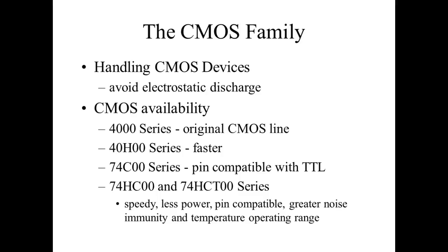So in the old days, 4000 series was CMOS, 7400 series was TTL, and they were not compatible. You couldn't mix them in the same circuit without going through what they call a level converter chip. And then they came out with the 74HC, and that blew everything out of the water, because what do you think the C stands for? CMOS, with a 7400 series. Man, this blew me bad. Because they're pin compatible, but they will not drive TTL.